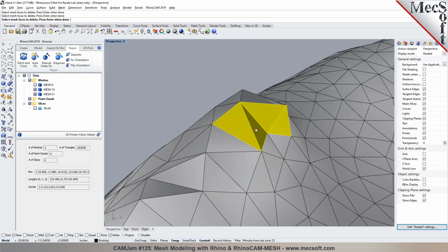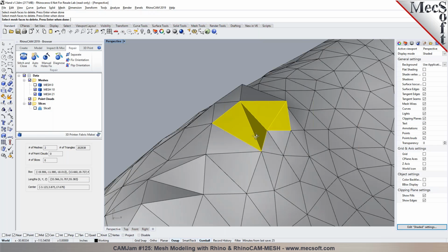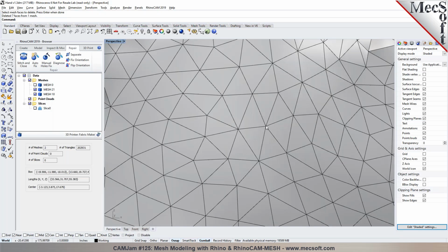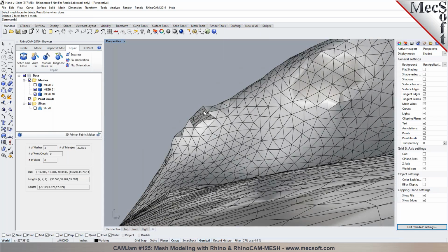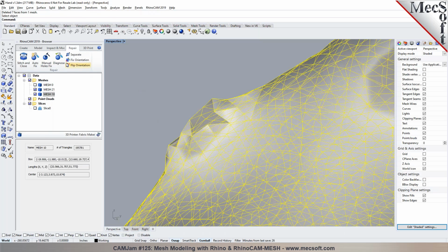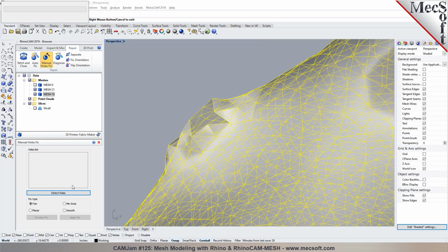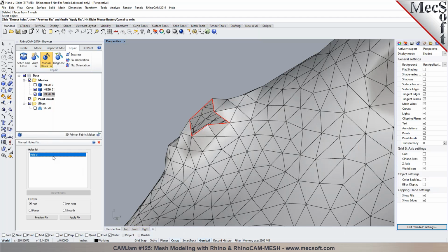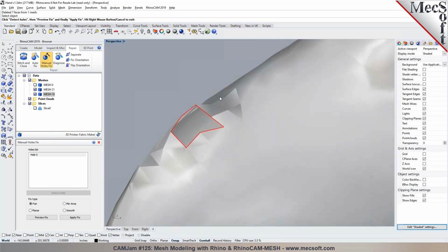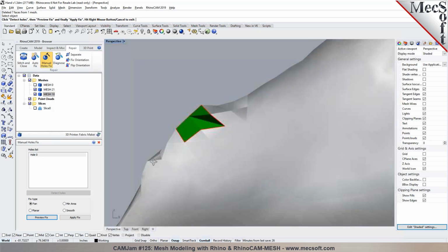Uh-huh. Just pick those. Right? I deleted them right there. Right. So now if I do a manual hole fix, I'll pick this. Detect holes. It's going to detect this hole right here, right? Right. And let me hide the mesh wire, so it just makes it easier for us to see it. I can choose how you want it to be. If you say preview, a fan will basically, this is how it's going to put a fix right there.